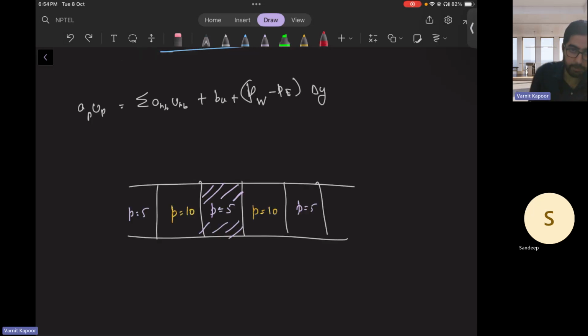If this kind of scenario occurs, it is not always that checkerboarding will happen. But if this kind of pattern develops, that for the considered cell, both left and right faces are of equal values, then checkerboarding will happen. So that means here, gradient of P will become zero, correct? Which creates unwanted oscillations.